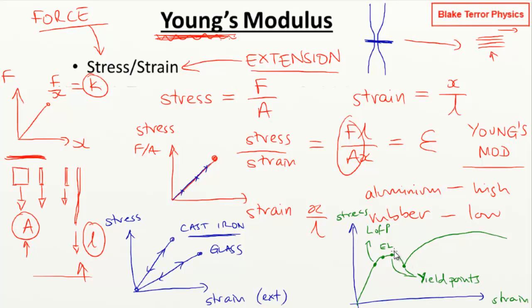I can't say I'm that well versed in exactly what's going on here, but the behavior of the material, like I say, you can get this accelerated extension. And then beyond that, you've got this high point here. This is the maximum stress, the most pressure that you can apply. So the greatest force to some extent, depending on the area. This is your ultimate tensile strength. So tensile, so for stretching, the ultimate tensile strength of the material. That's the most load it can hold.